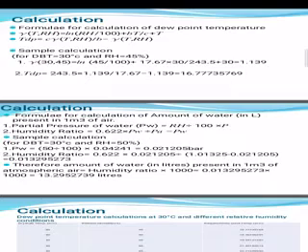This calculation forms an important part of this project, as it helps us to determine at what temperature the Peltier device must be maintained in order to condense the humidity present in the given atmospheric condition. So I'll tell you what the dew point temperature is. The dew point temperature is the temperature at which humidity in the air starts condensing at the same rate at which it is evaporating at a given constant pressure.